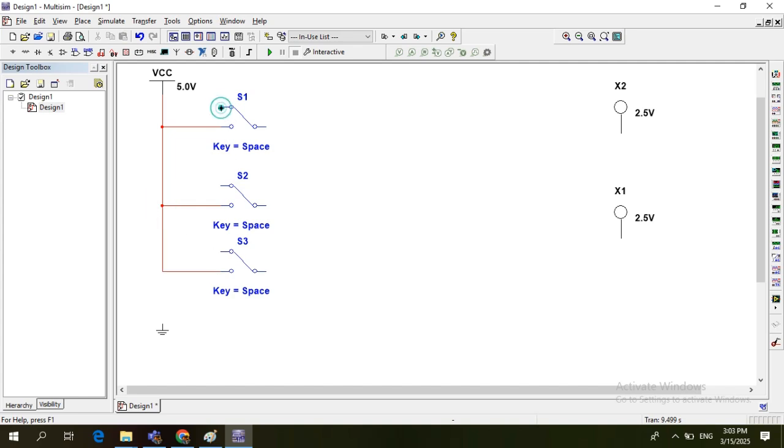Now again I'm going to connect the ground for these switches. So there is an open terminal I have selected in power. So when I press the switch, the switch will get the power and the switch will be activated. And the closed terminal I have selected in the ground. It seems okay now. Now I should go to select more components.